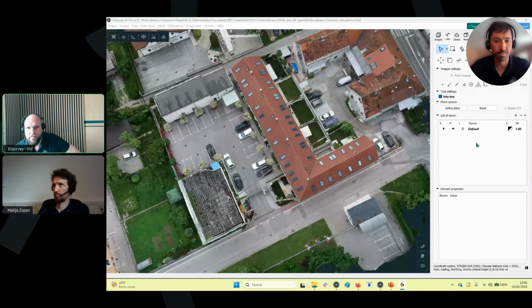This is the most useful and the most intended functionality of the transform tool, moving the projects or data vertically, for example, from the ellipsoidal coordinate system to geoid, or if we just have everything at 0 elevation, to bring it up to the real world coordinates.